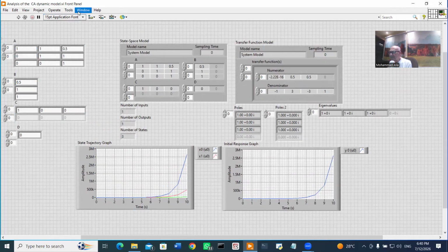So this is the time representation, which shows you the dynamics of the Kalman filter with a constant acceleration model. Note here that the number of states is 3. So this matrix will be 3 rows by 3 columns. And here also B must be 3 rows.